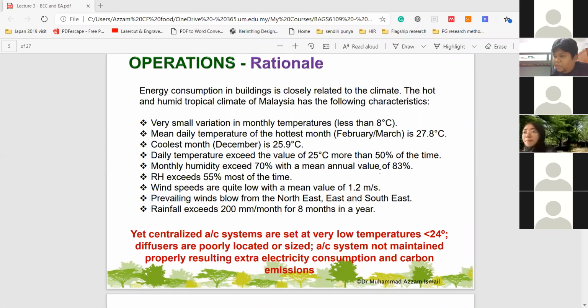It's only about 4 degrees, you know. So the solar angle is very, very shallow for Malaysia. For Singapore, even more shallow. So when you design something, a roof, let's say, you know for sure the roof at whatever angle will get illuminated by the sun very easily. So there's not a lot of shading unless you get shading from big trees or big buildings around you.